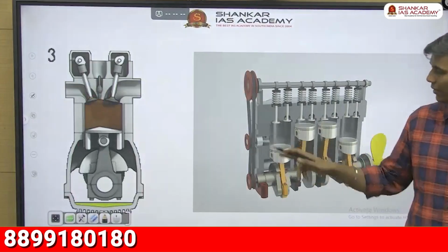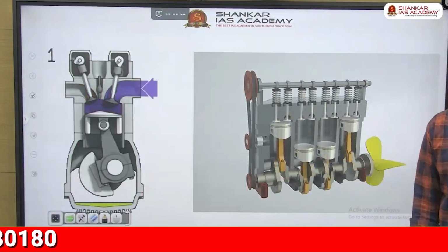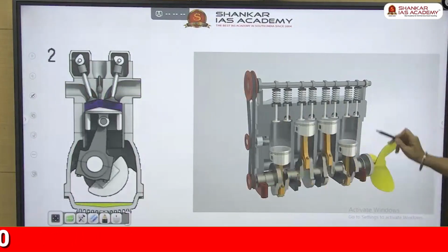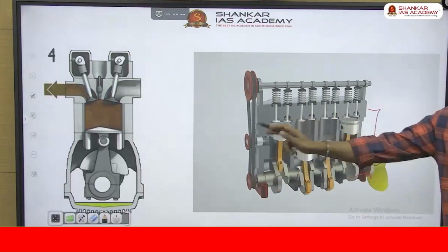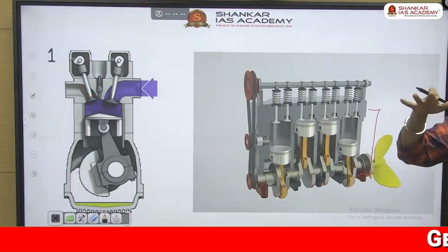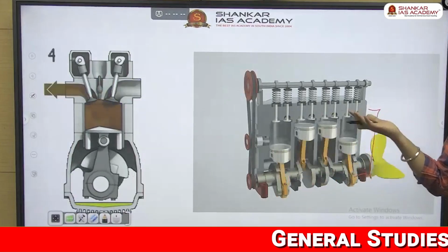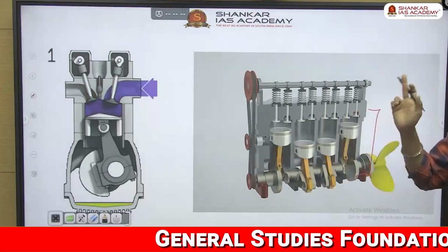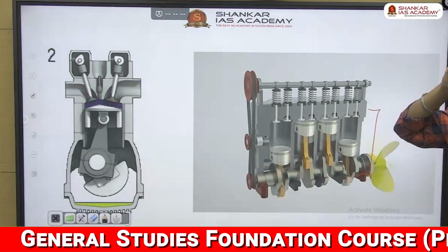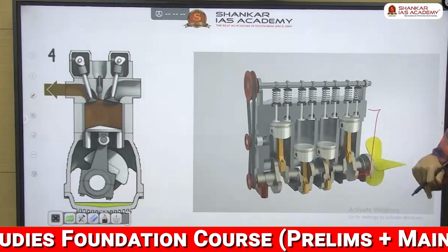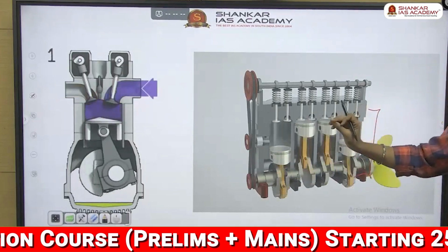Which means, do you see a spark plug here for a diesel engine? No, they are having more CC, correct? 1200, 1600. They're tall engines, they have more space inside, they have more compression, and because of high compression, the fuel will automatically burn. And also you can connect it with the ignition temperature. For diesel, ignition temperature is lesser. A quick compression can cause the diesel to burn.